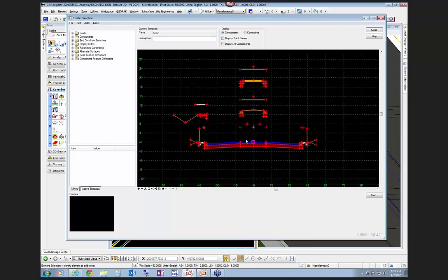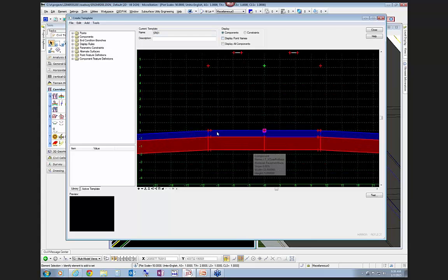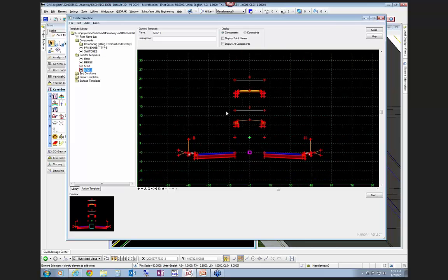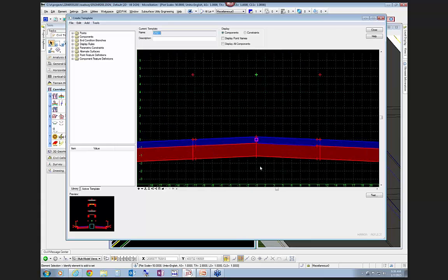And this crossover component now has, and I had modified this, if you look at the way it actually comes across in our template library, it looks like this. Imagine this without the joined pavements. What you'll see now are these two new crossover points in here, and then there's a crowned point here. So it comes over as though you would have a normal crowned median.